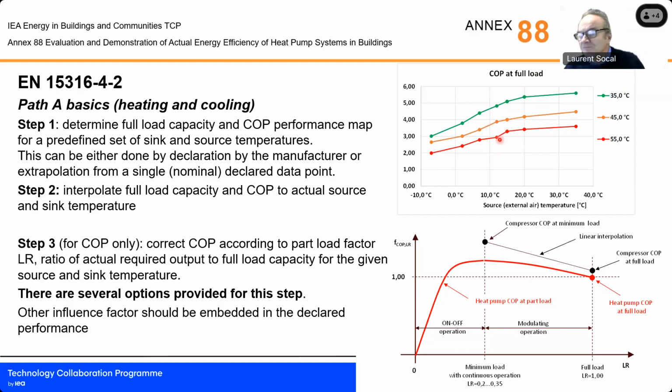And very often, you can see one issue here quickly: usually you have testing points for heat pumps in this area, so cold temperature, and very few remember that you use this heat pump also for domestic hot water, so you would need at least one testing point in the area of summer temperatures. This very often is manufacturer declared.